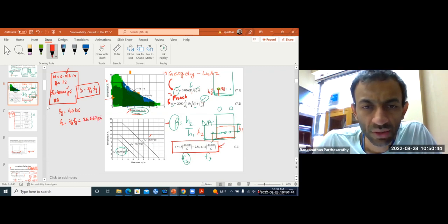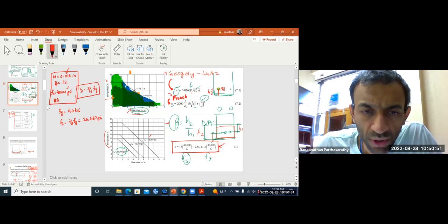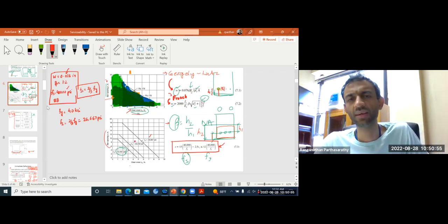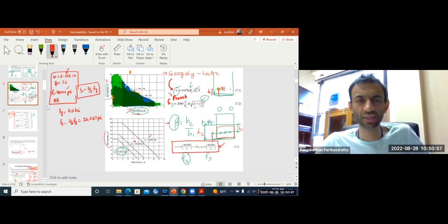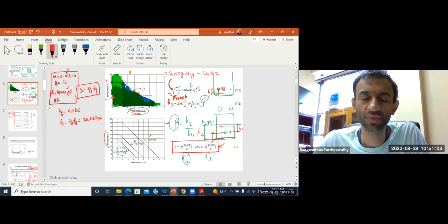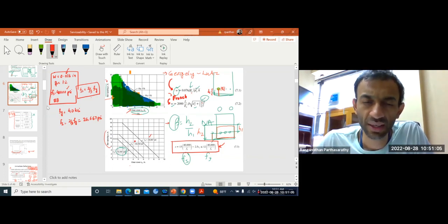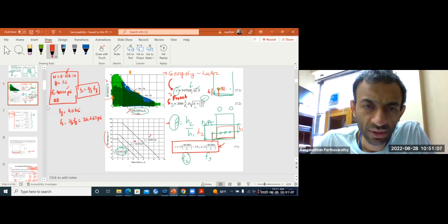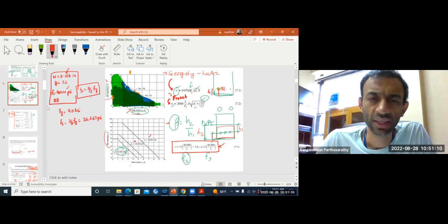So for all of these values, you have your bar spacing versus clear cover. Whatever you provide, that number should be inside the area enclosed by the straight line. Sorry, not outside, of course. Outside you violated the specification. So you have to stay inside.